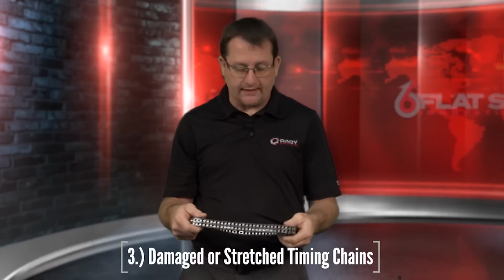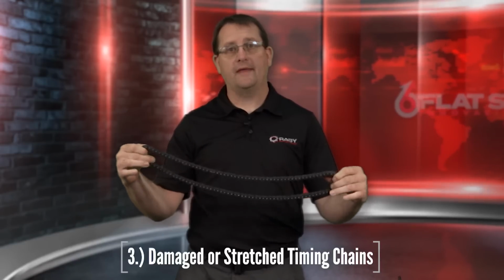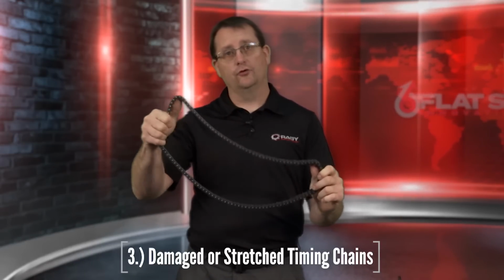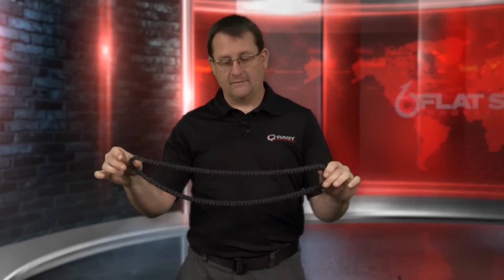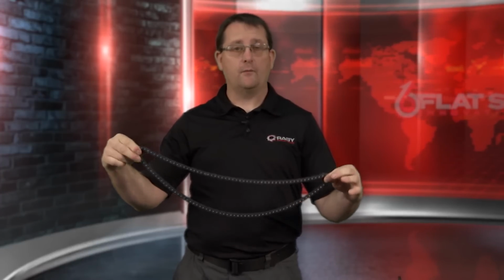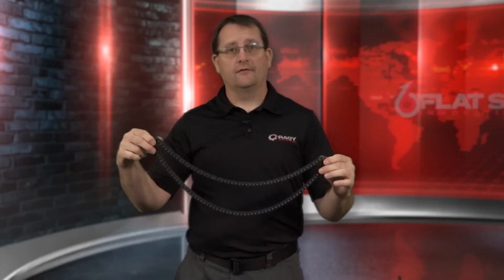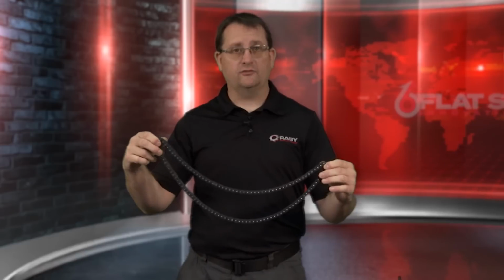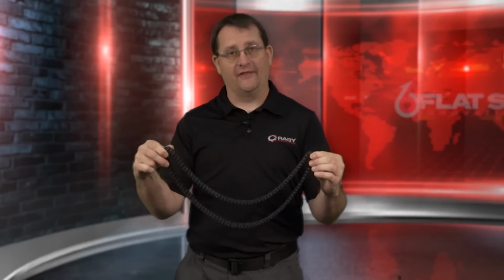The third thing that comes into play with the three-chain engines is these master timing chains. These will go from the intermediate shaft out to and around the intake cam, out to and around the exhaust cam. These timing chains are not good quality. We've seen these at 30, 40, 50,000 miles losing their tension. We've seen them stretch. We've seen them lose chain links. We've seen them snap in half. I've got a little bit of history with all of that stuff.